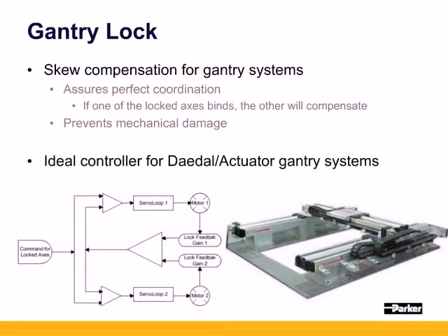And depending on the stiffness of your cross axis can also cause orthogonality errors, as you have a crabbing effect with X' always slightly behind the X axis. The ACR9000's Gantry lock allows both motors to receive the same commanded position at the same time. In addition to monitoring its own axis error, it also receives the error from the other axis. This keeps both X and X' moving in parallel, preventing orthogonality errors or crabbing of the Gantry, and enables both motors to be run at full performance for high accuracy and increased machine throughput.